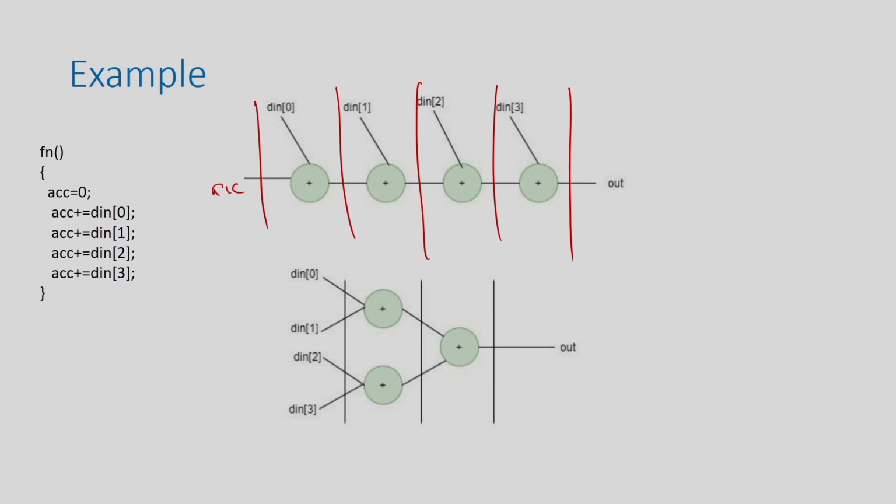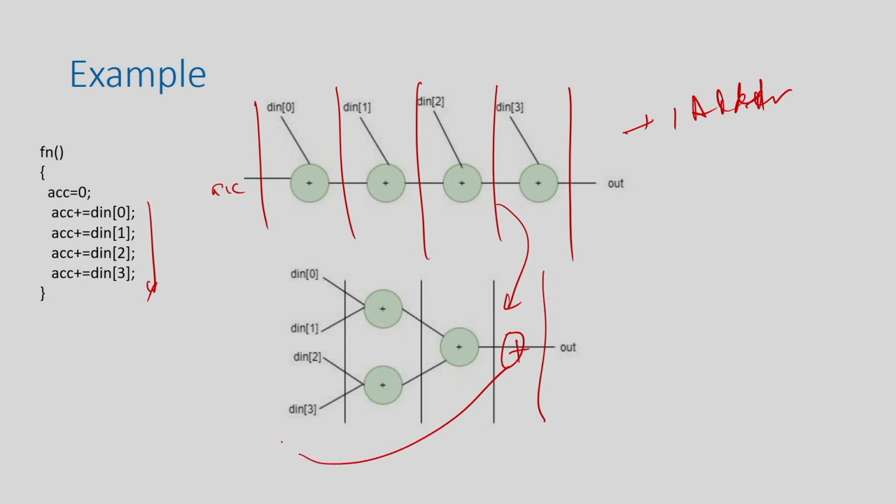Apparently, you can still execute this using one adder, because you can multiplex the inputs of this adder, time division multiplexing of the inputs. Okay. So, that is one possibility, but usually once you have this, you can rewrite this dependency into this, right. Now you can see that instead of 4 cycles I can execute in fewer; there is a mistake here. So, the ACC will come here in 3 cycles, right. It was 4 cycles, this is 3 cycles.